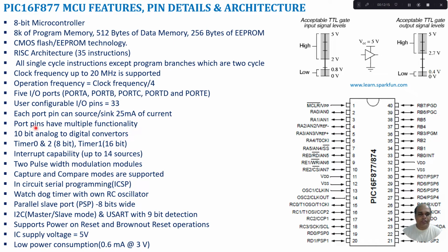The resolution of your ADC will be about 4.88 millivolt for a reference voltage of 5 volt. If I keep a reference voltage of 5 volt, then our input can swing between 0 to 5 volt. We can also change the reference voltage for the ADC. By changing the reference voltage, I can increase the resolution of your ADC. Resolution is nothing but the smallest voltage change which can be represented as a proper binary output.